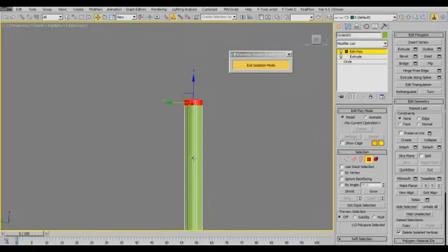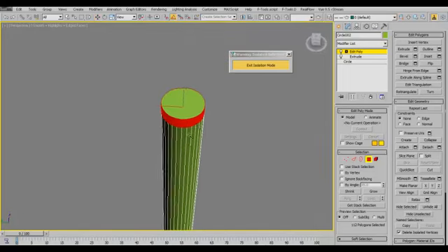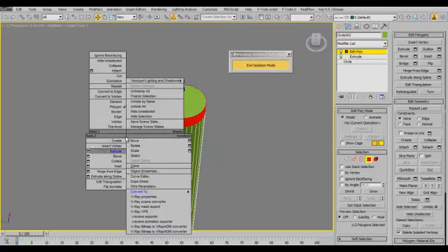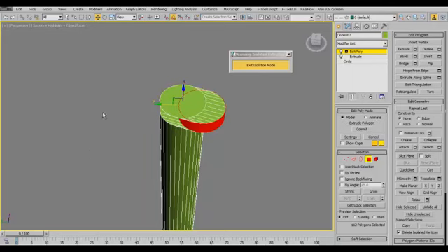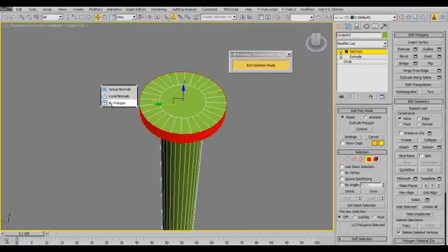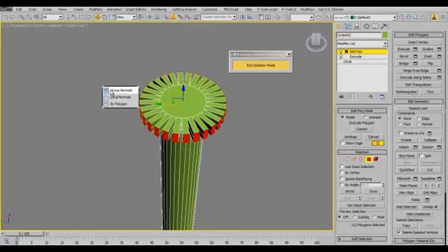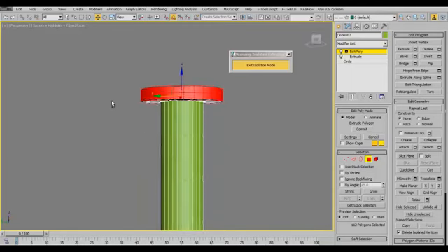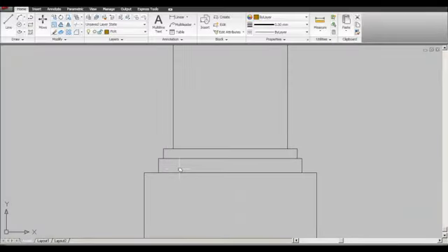And what we do is, let's come to our perspective view, and what we do is we use an extrude, and let's do the extrude. You have to pick the extrude from this small window here. Then you now select, tell it to choose local normals, the other options, which is the polygon, depending on what you're trying to do, and this is the group, and of course this is what we want to achieve. So what we do is we tell it to create it to, like, say a 50. Let's take a look at the size here. This is 50, so we use a 50,